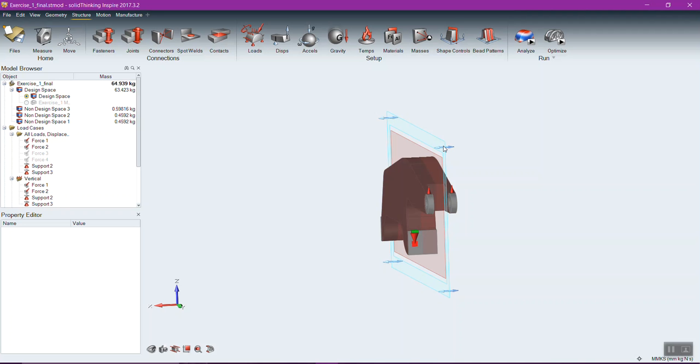Casting is the same way. Casting, you're pouring a molten liquid, be it plastic or metal or whatever, into a cavity, and then you're allowing that to cool, and then you have to remove that from that cavity. So there are limits to the manufacturability of it. You can't have undercuts, you can't have hollows inside there. There's no way to pour something into a mold and have it hollow on the inside. It just can't be done.